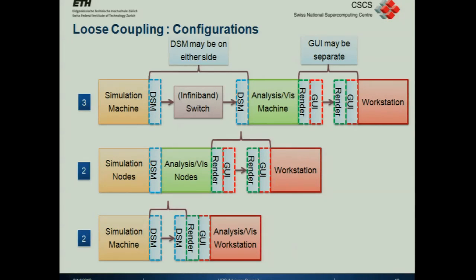And then because we're using a ParaView client-server framework, we can have the GUI running on your workstation, we can have a Viz cluster doing this, and we can have the big Cray doing that. Or we actually find that this is the one we use all the time. We have the Cray, for example, doing simulation and analysis, or the Viz cluster doing simulation and analysis, and the workstation on the desktop. And you could even have all of this going on just on the desktop. In fact, you could do the whole thing on just one machine if you want to, but I didn't bother including that. It's flexible, and as long as you've got a network connection between them, you can do it whichever way you like.